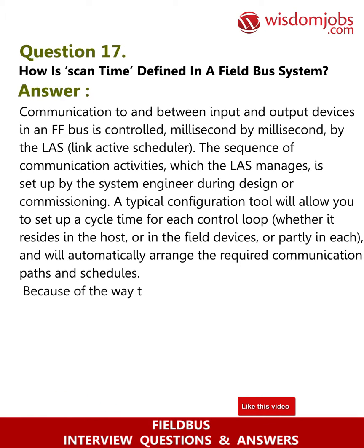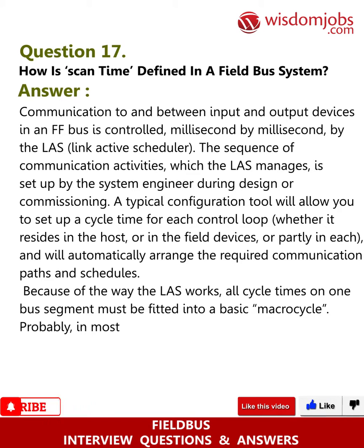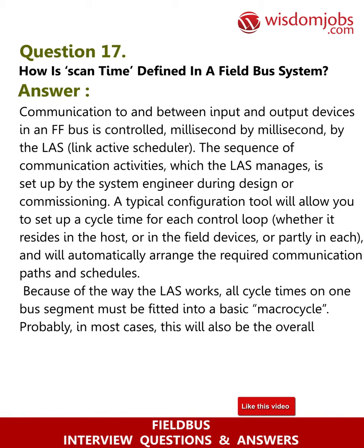Because of the way the LAS works, all cycle times on one bus segment must be fitted into a basic macro cycle. Probably, in most cases, this will also be the overall scan cycle time for control loops on that segment.